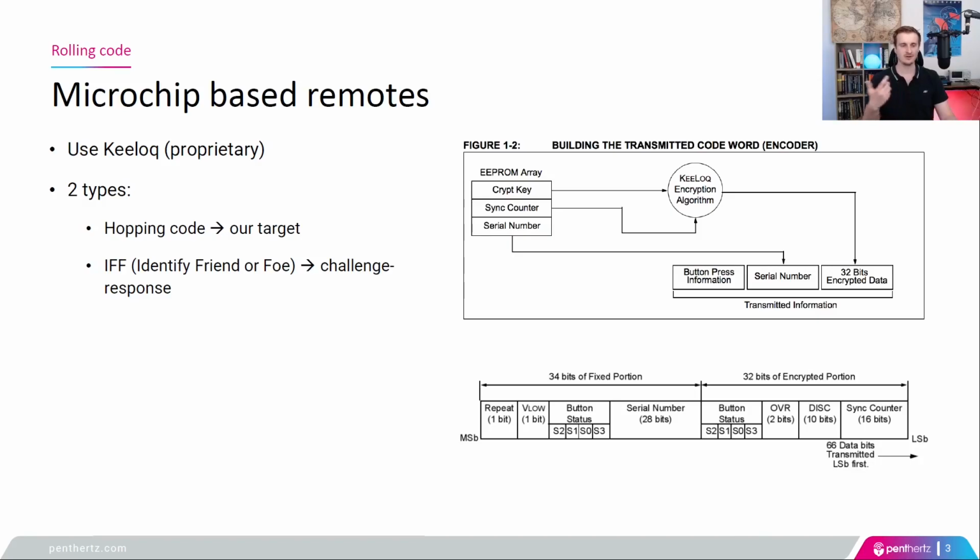So finally, your encrypted part will also be different each time. And you also have the representation of the clear text data. As we saw before with URH, you can correct those bits a little in order to make some sense of them. As I saw just before, without any documentation I was trying to blindly reverse engineer the communication. But once you have the documentation, you can try to match the data sent over the air a little more.